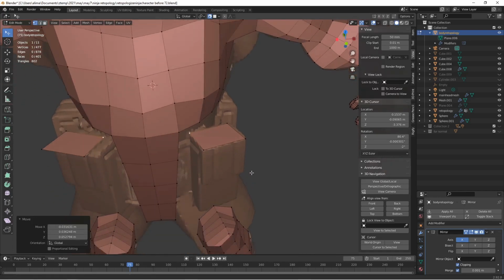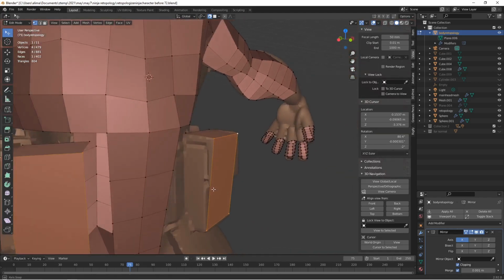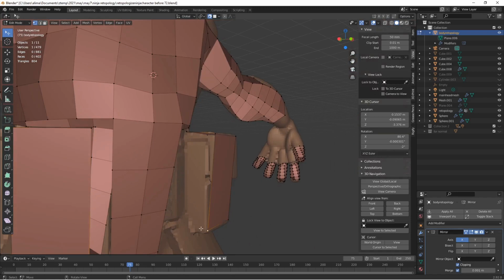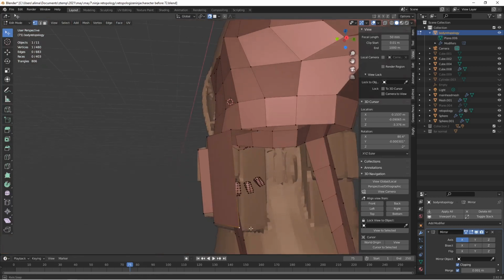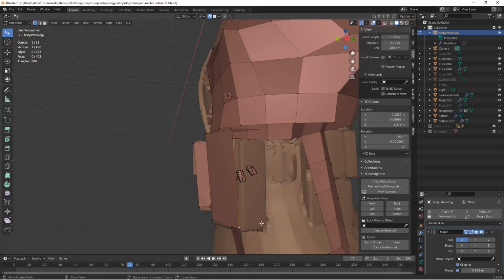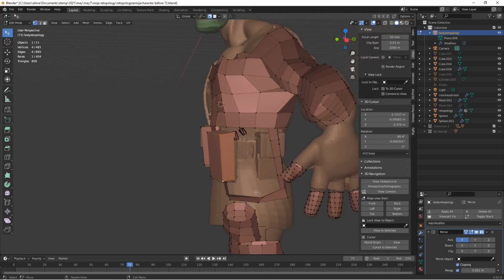To move that. So now I'm selecting here, holding Control. I'm going to select here, hold Shift, then press F to fill. Select here, holding Control, selecting here, pressing F to fill, left click to deselect. I'll select here, hold Control, right click. Then I'll select these here as well as here, then press F to fill.